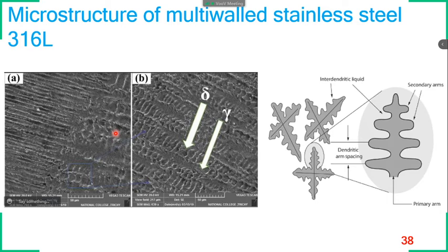As the grains become coarser, it is more suitable for high temperature application. Whereas for normal applications, wherever we need more strength, ductility and microhardness, fine grain is more preferable. But still it is a very challenging task to achieve fine grain structure, especially in WAAM components.